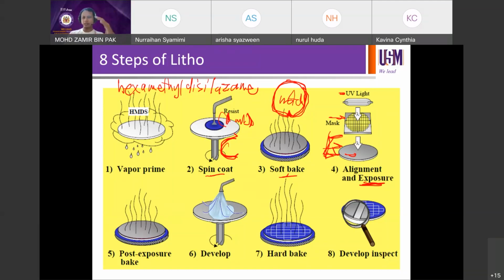The robot arm, the system itself, the scanner, the track, and whatever equipment comes after this process, all of them have to start off with the right home position. So this notch is considered 0 degrees, or the home position, before we rotate throughout the circumference to get back to the same point. Before you expose, the wafer goes into the scanner before we print the pattern, so it has to do some alignment.